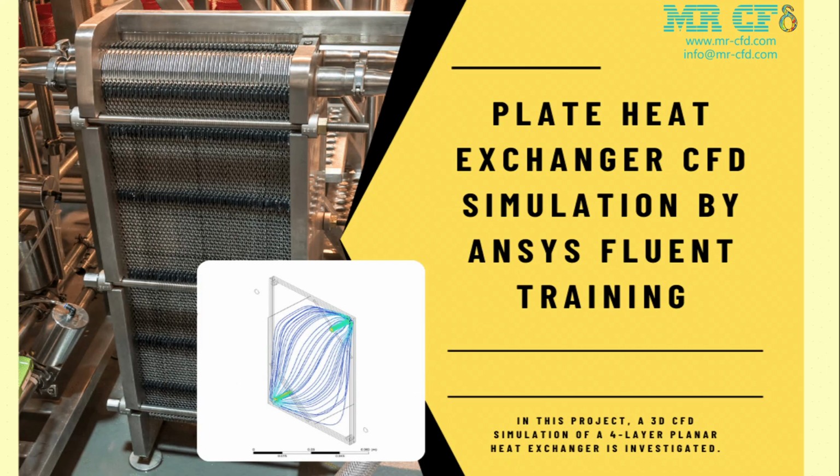In this project, a three-dimensional CFD simulation of a four-layer plate heat exchanger is investigated by ANSYS Fluent software. A steady hot and cold water flows enter the planar domain and move through the heat exchanging region. These flows exchange heat, which leads to temperature difference reduction. Both flows exit the heat exchanging domain with approximately equal temperature, which is 282 Kelvin.